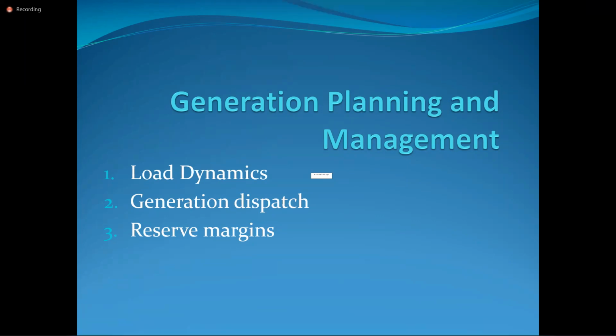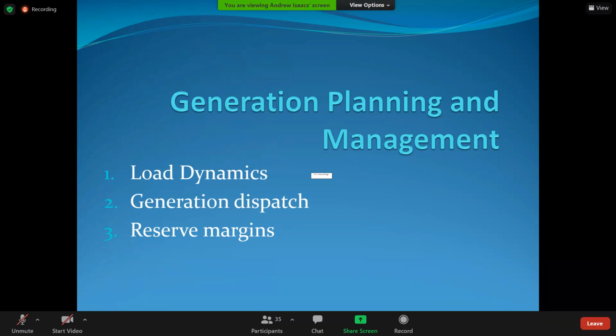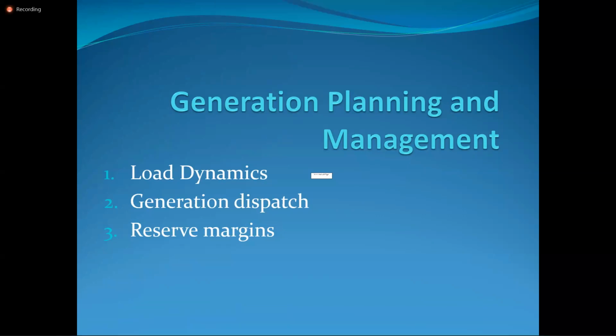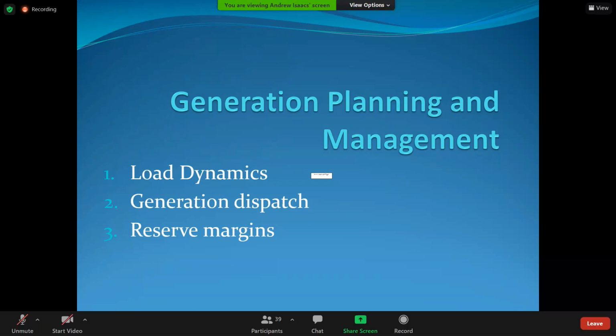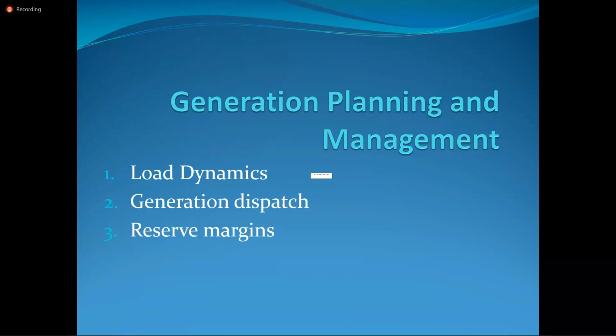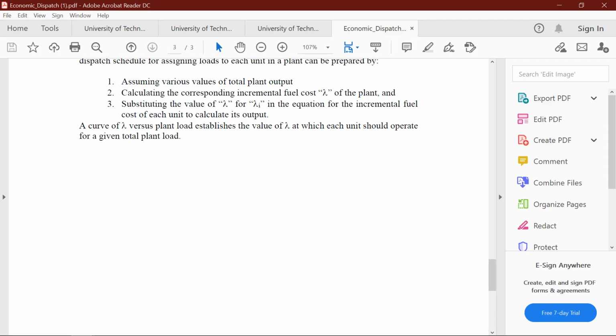In other words, at the point where two media are connected. So if I am moving from the line going towards the cable, then at the line cable junction, I'm going to have reflection, which would therefore be the reflection coefficient based on the line to the cable, because the signal is in the line heading to the cable.